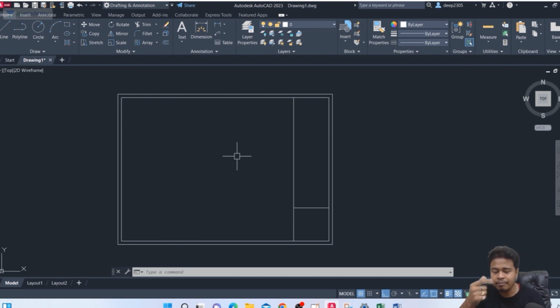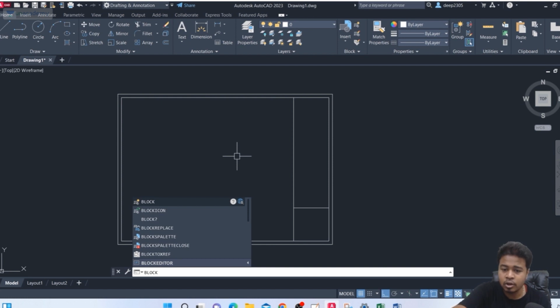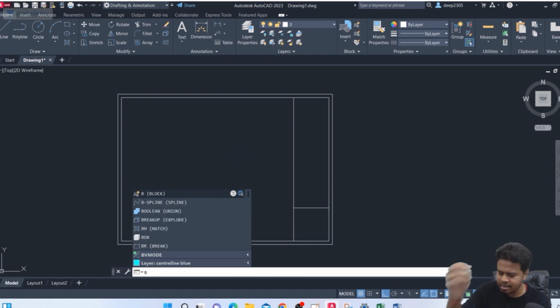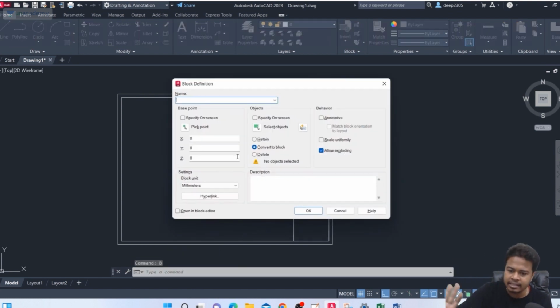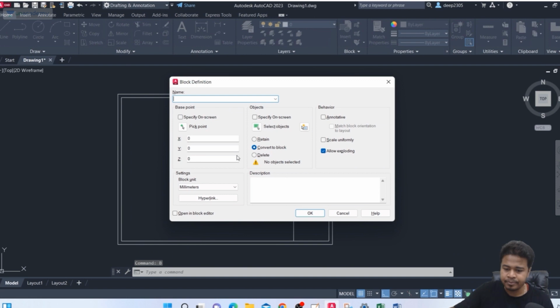You have to create a block. So go to, not W block, create a block. BLOCK, the shortcut key is B. I will explain about the block in the upcoming chapter. That's not an issue. So B, enter. Just follow the step. Name it title block.